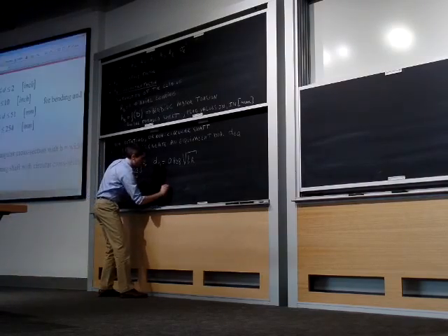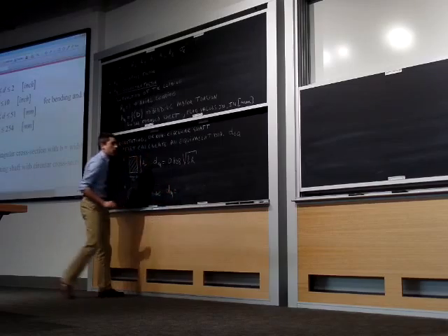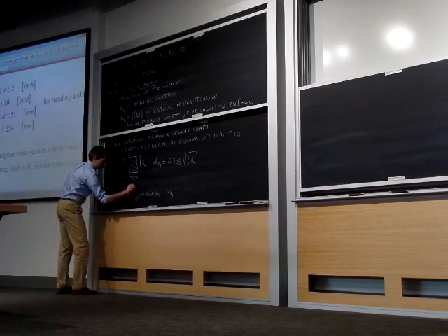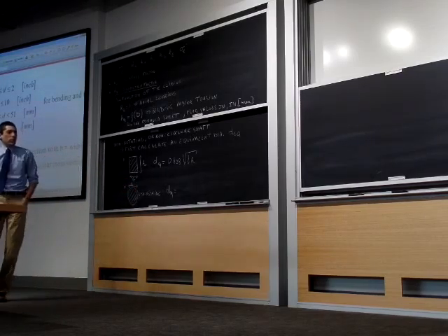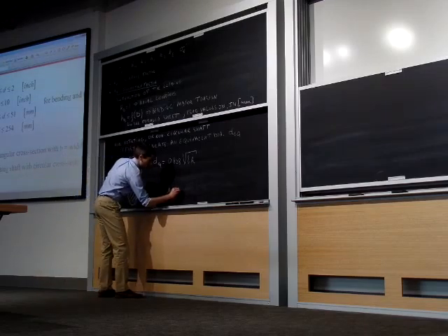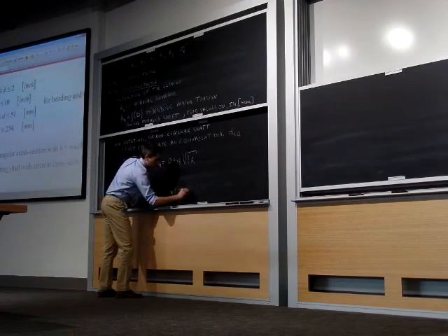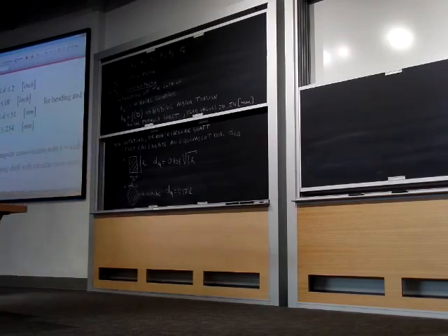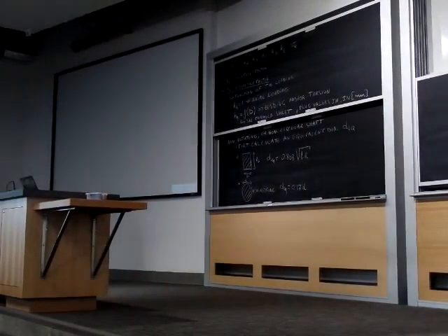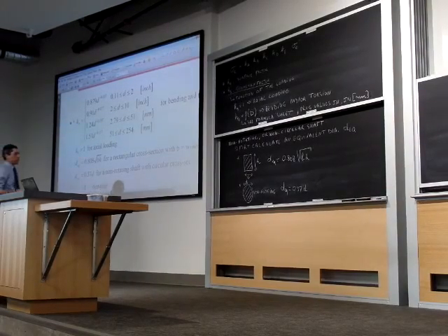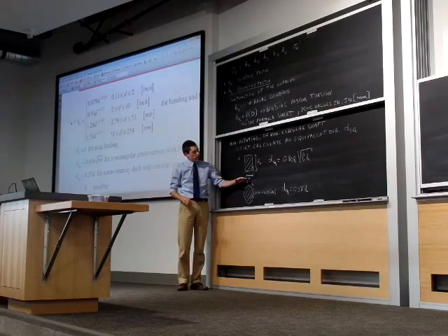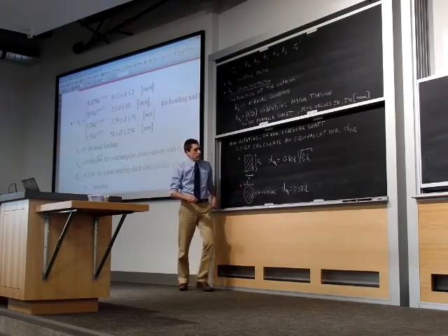And the equivalent diameter there is, and this is lowercase d, is then 0.37 d. And you can see intuitively why, if the shaft is non-rotating, we have to account for that in our fatigue calculation, because say that this shaft is non-rotating, okay?